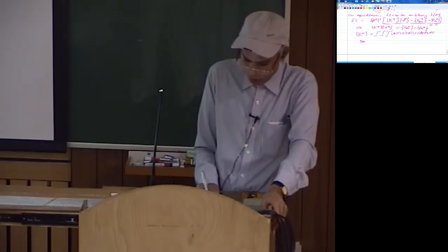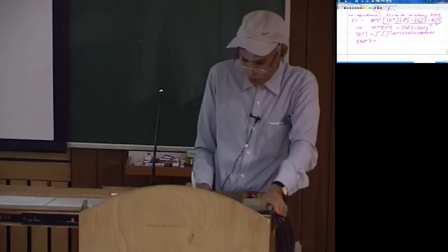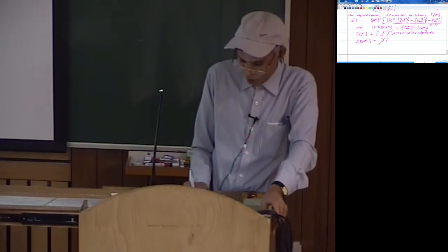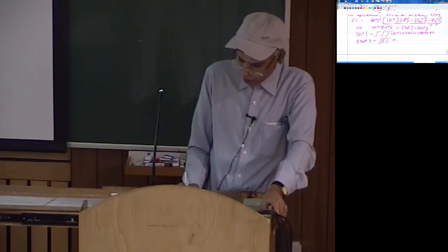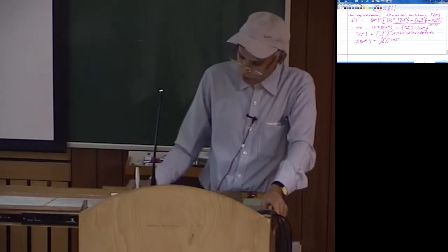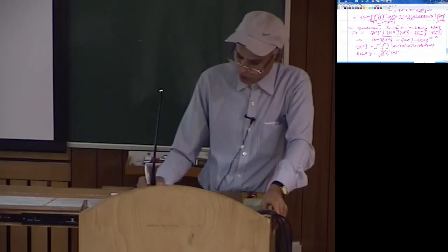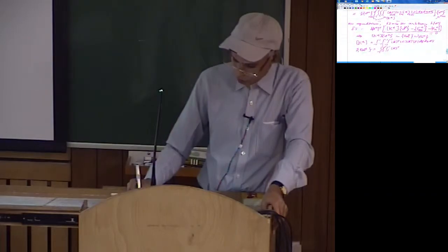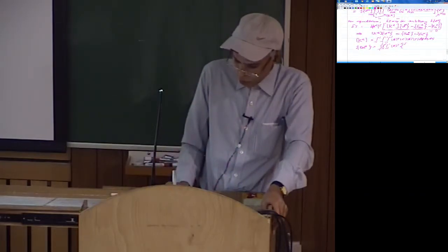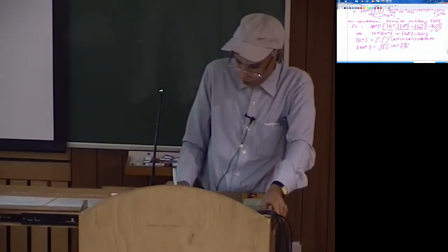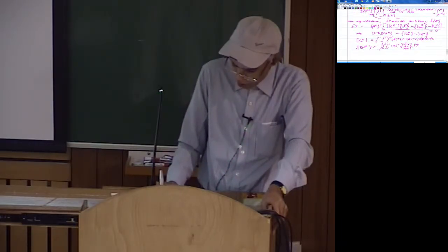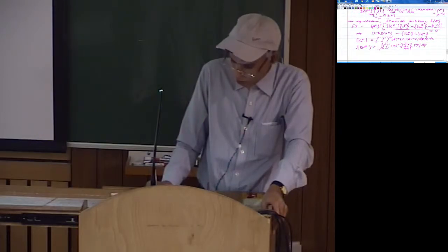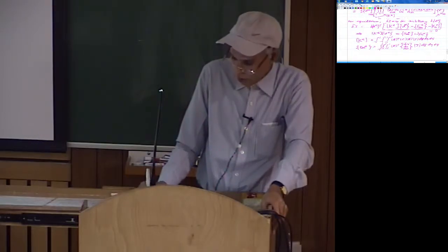Your F external for the element is again this triple integral -1 to +1, and then you have H transpose, essentially this is the term which I refer to as F external. So H transpose into body force FBX, FBY, FBZ, and then this again can be written as determinant of J into d xi d eta and d zeta.